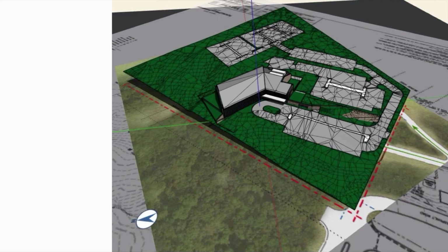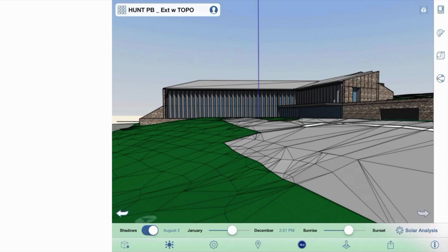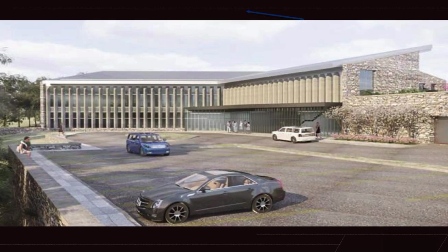We can change the materials of them because the meshes are selectable, and you can change all that geometry. You can actually work right off of that geometry. You can modify that geometry. You can delete it, and you can change the materials and effectively get geometry which is in the correct location and is exactly basically your topography that you created in Revit.